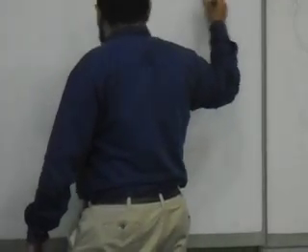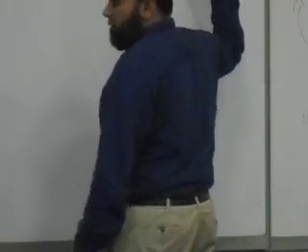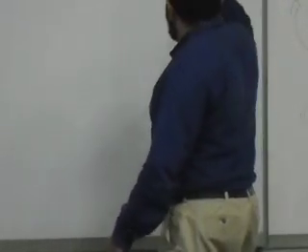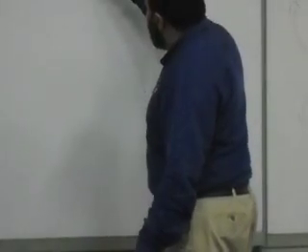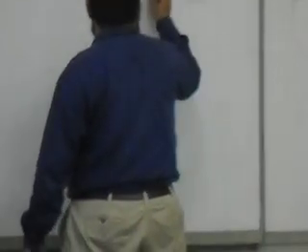So he actually did the job for me. He gave me these reactions. And again, this neoprene pad is actually a roller support, as you mentioned, please. So this is 16K, and this is 20K. That's a triangle. The height of this triangle is 3 kips per feet. This is 6 feet, and this is 18 feet.